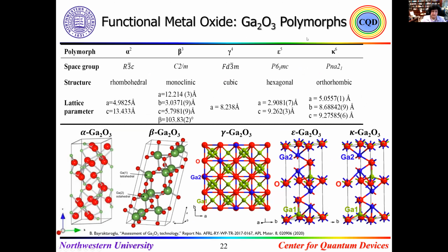As we know, gallium oxide is a polymorph. And what is the problem of the oxide? It is similar to the lead phosphate that I worked on. The symmetry is low. When the symmetry is low, it is beautiful for different applications, but unfortunately it is very hard to make devices, especially laser and LED, on this material. At the same time, one of the big problems, again, is doping. Gallium oxide has different polymorphs that most of you are familiar with, and you have to know that.